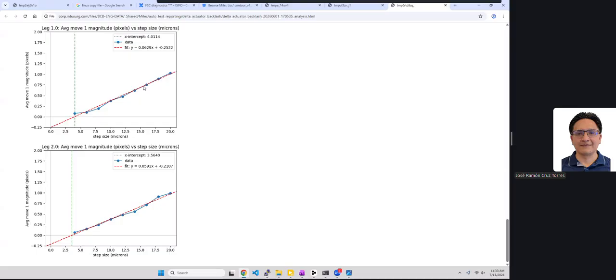If you tell it to move forward 10 microns, and then tell it to move backwards 10 microns, that backwards move has to overcome the backlash in the gearbox. So it might move 9 microns instead, or 8 microns or something like that, but never overshoot, right? But that's the trivial case.